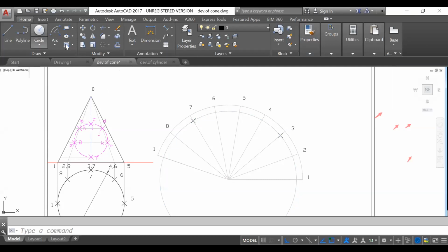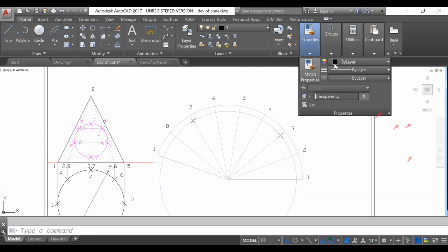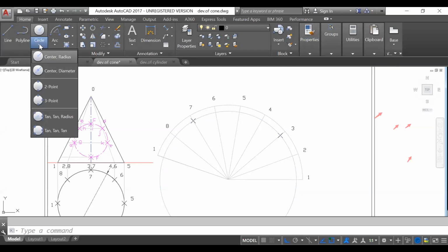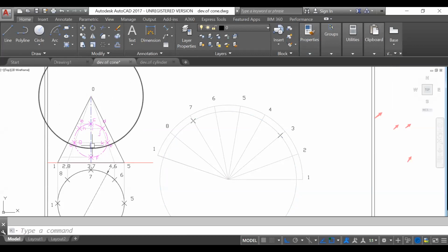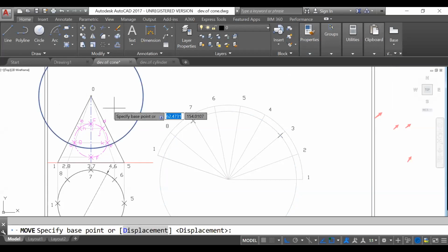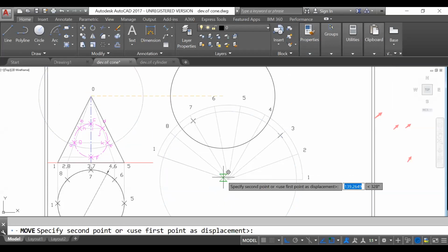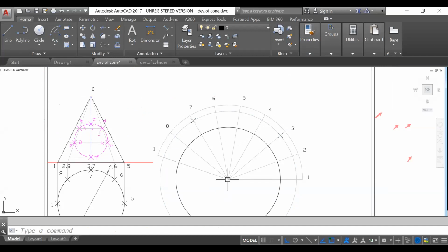Now, next part, next circle, I will take this with this one. Okay. So the next circle is from this to this. So for this, you will get A, G, K, E, all the points, 4 points you have to mark simultaneously. So go to the move command, select the circle, then this one, put it here. Okay. Now, how can we join it? That AG is on 2, 8, and then this KE is on 4, 6. So 2, 8 and 4, 6 we have to mark.